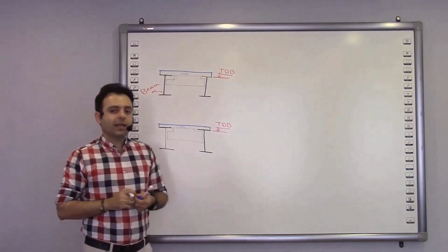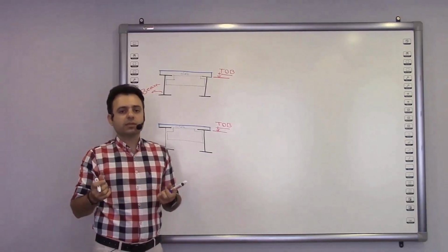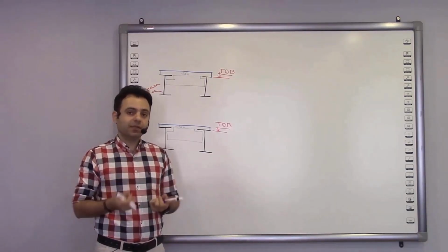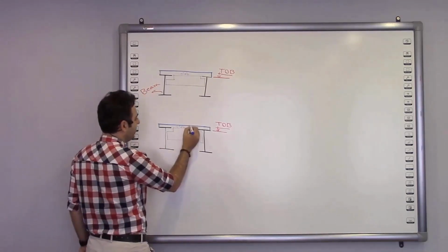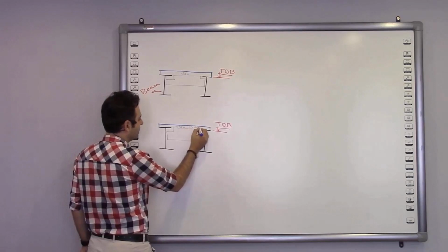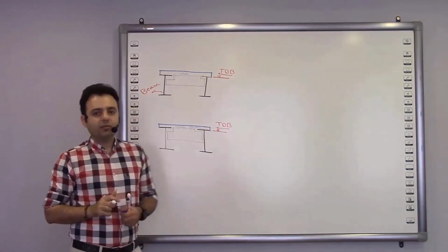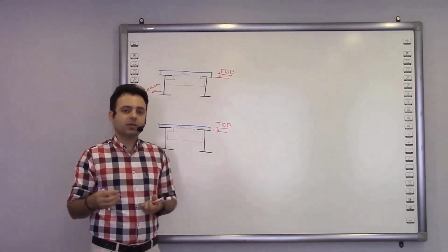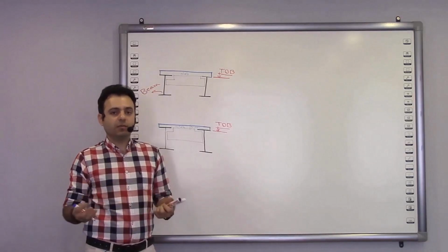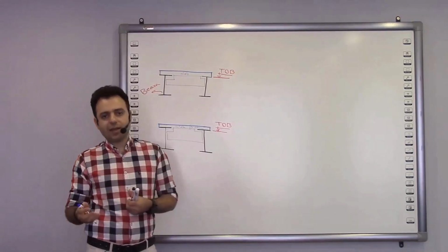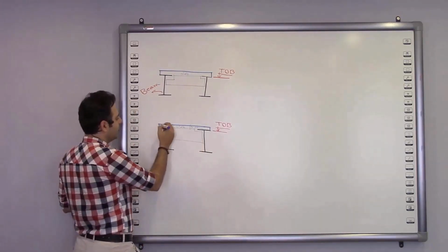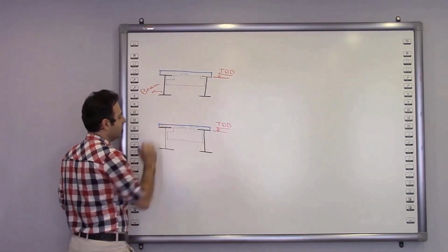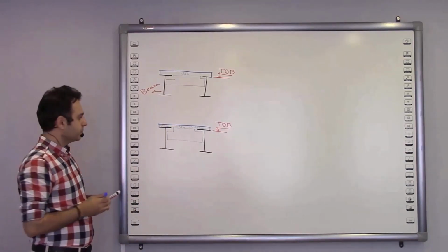Now, what is the thickness of this slab? Well, it's usually specified based on the structure. Well, for example, let's imagine it's between 5 to 50 centimeters. Well, in our practices and in the phase 2, we usually count it as 10 centimeters when we don't have enough information about the slab. It means the normal amount of it is 10 centimeters.